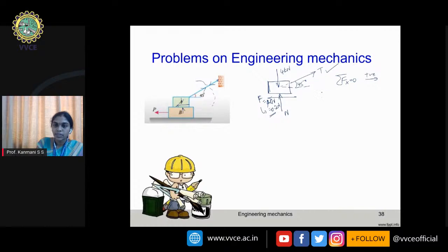So first I will apply T cos 45. That's the horizontal component, which is positive. This is purely vertical, so no horizontal reaction. This is also purely vertical, no horizontal reaction. Only horizontal force we have is F, which is moving towards left, hence I'll put minus F, or directly write 0.2 times N equal to 0.